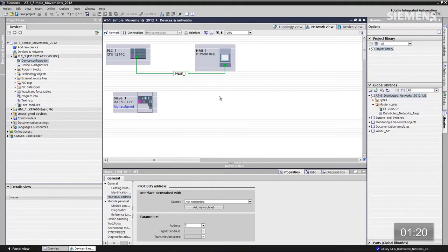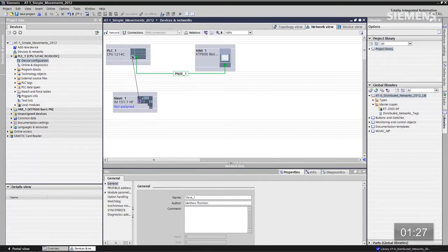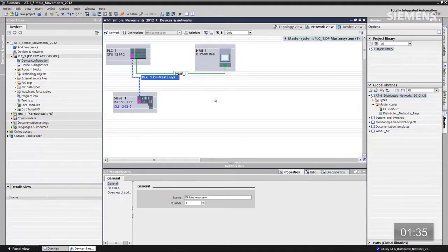The next logical step is networking. So let's mouse over the Profibus interface of this rack. Let's drag it to the master module. When I let go of it, it'll auto-create the logical physical connections. The Profibus network is done. Let's move on. Okay, PROFINET.